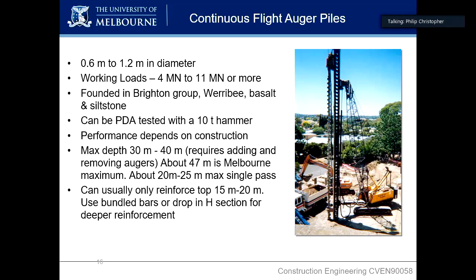The problem with this, or the challenges I should say, is you're not drilling into a whole lot of rock with this, because imagine trying to drive your corkscrew into 10 metres of rock. It's just not reasonable. A bored pile can dig out rock because it does a little bit at a time. So this method is only good for extremely weathered to maybe a little bit of moderately weathered rock, a few metres at tops.